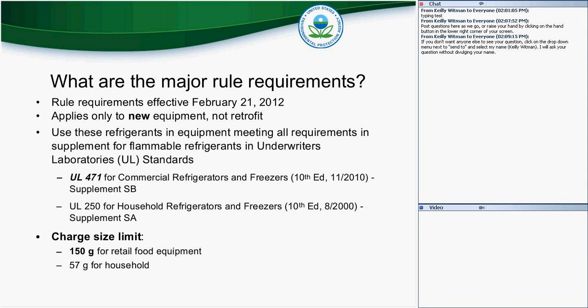Right now, I don't know of a single recovery machine that is designated for hydrocarbons and is certified to 608. That said, I think there was at least one company at the recent ASHRAE Expo in Chicago that was displaying such equipment, and I did talk to a couple others who I think are developing recovery equipment and working on that.